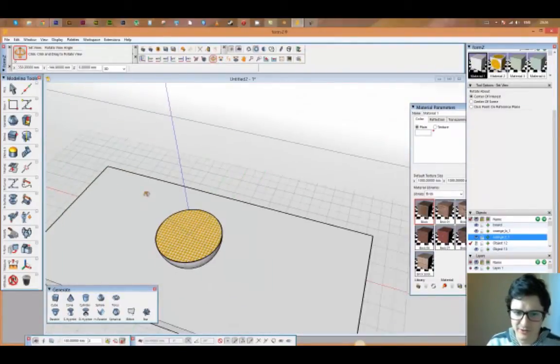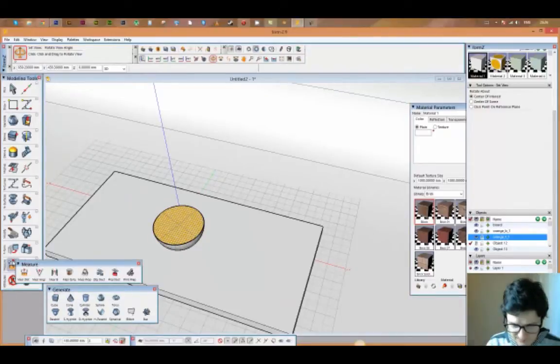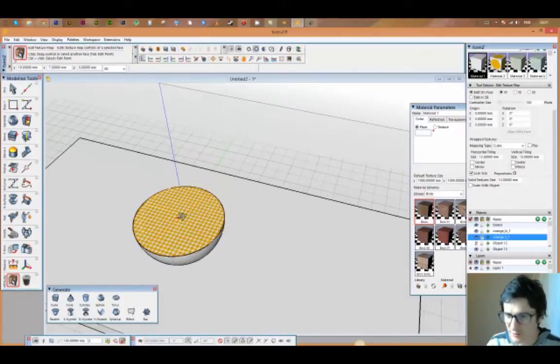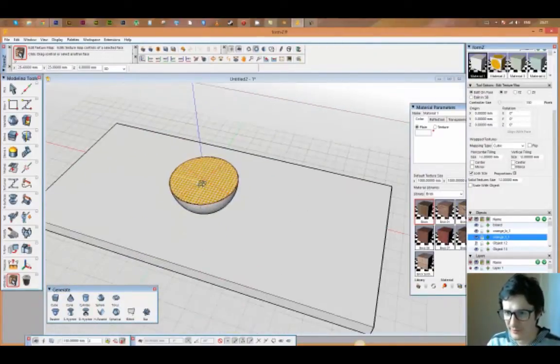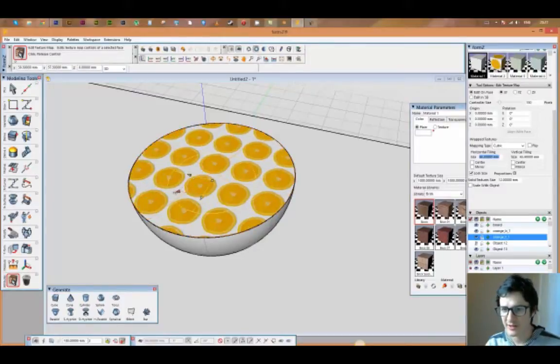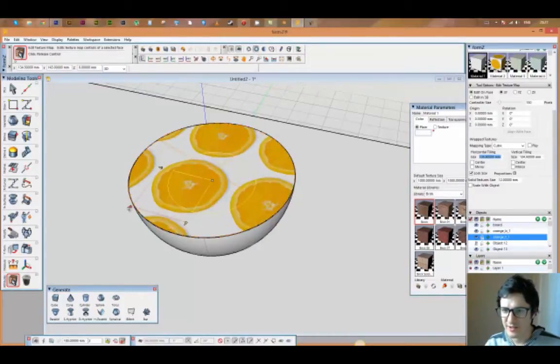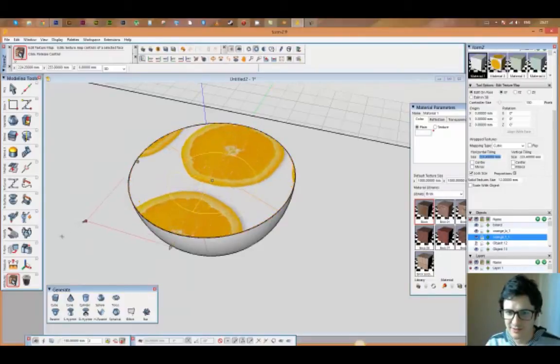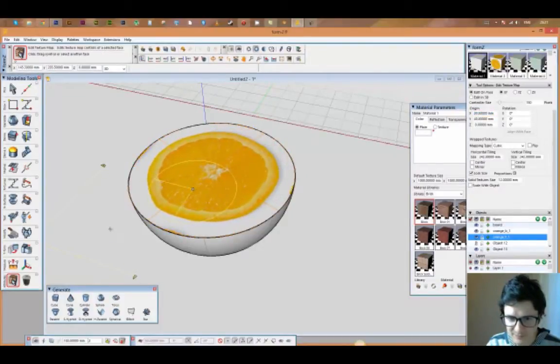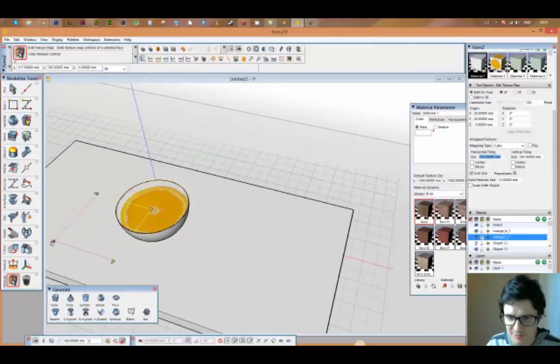Now, what I'll need to do is use the Edit Texture tool, which is in this panel here, Edit Texture. And you can see, you might have to zoom out to find where those controls are, but for me, they've landed up right here. That's great. Now, I want to use this diagonal one here, and drag that out, and that'll drag it out in a uniform way. And just dragging it out till it gets to roughly the right size for the orange face, and then repositioning it so that it covers that. And just continuing to adjust it till I get it exactly right.